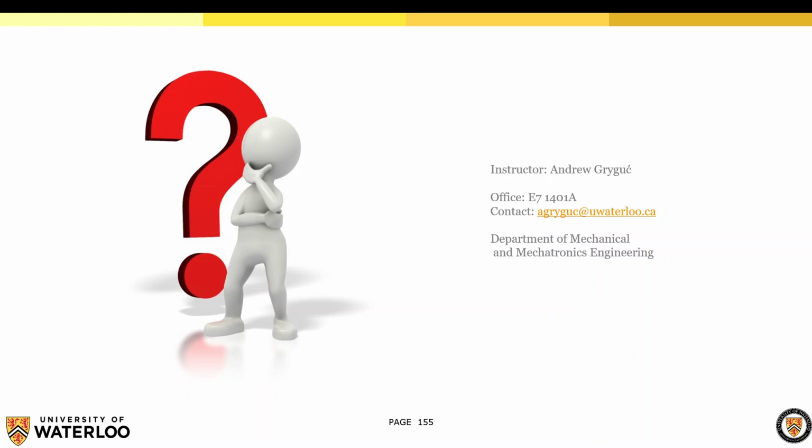Yes, you can. In the software, there's a fatigue option where effectively you run this normal static simulation, but you want to repeat the values from that simulation for a thousand cycles, not 100,000 cycles. And it's going to look at a different set of parameters instead of looking at the stress ratio. It's going to look at the key parameters on the material, which is other information you have to program in. You can edit it. If you have questions on stuff like that, send me an email.